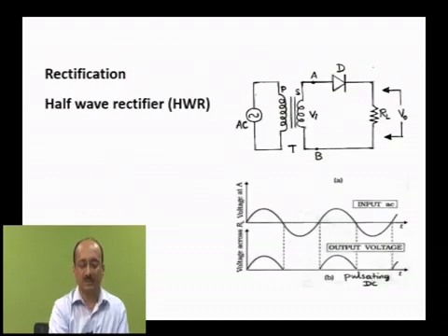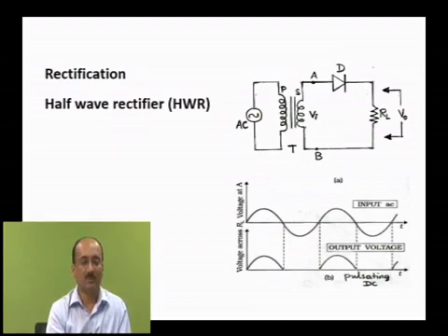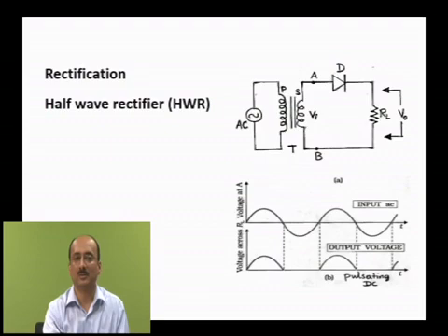And diode application, if we come to, rectification is a process. Basically rectification means converting an AC into DC. You may not get perfect DC, at least you will get pulsating DC. So as the diagram you can see here, there is this AC input, and using a transformer, step down transformer, you are going to decrease the voltage, and that is fed to the diode, and the diode will act like a rectifier.